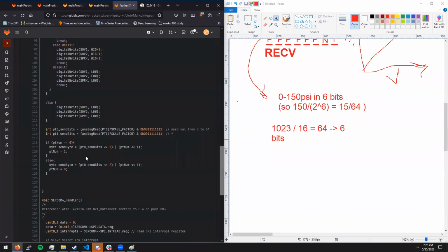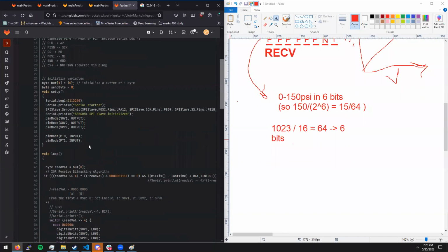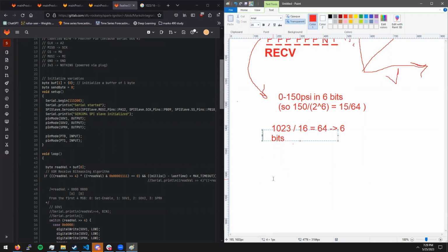And we also, it's not currently using the thermocouple right now. And the reason is because the thermocouple code, if no TC, because I2C has no timeout. So I2C has this quirk where it's not designed around there being errors in the communication. And since this was something shitty that I soldered and breadboarded together, I didn't feel confident that there might not be a wire that comes loose, or the chip itself burns out.